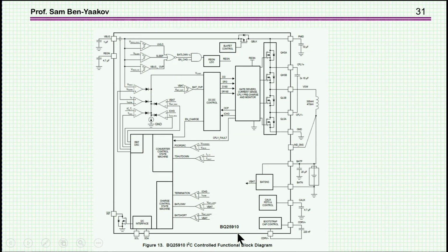So here's the unit they have, which is very nice because everything is within one unit. You have all these 4 transistors, all the drivers and control, of course, and obviously they do take care of the capacitor, which is here. This is the flying capacitor. And in this case, it's a 20 microfarad capacitor. This is because the current is fairly high, it's 6 amps. And then we have also a communication port here outside, so that you can control the unit and adjust the current, etc.